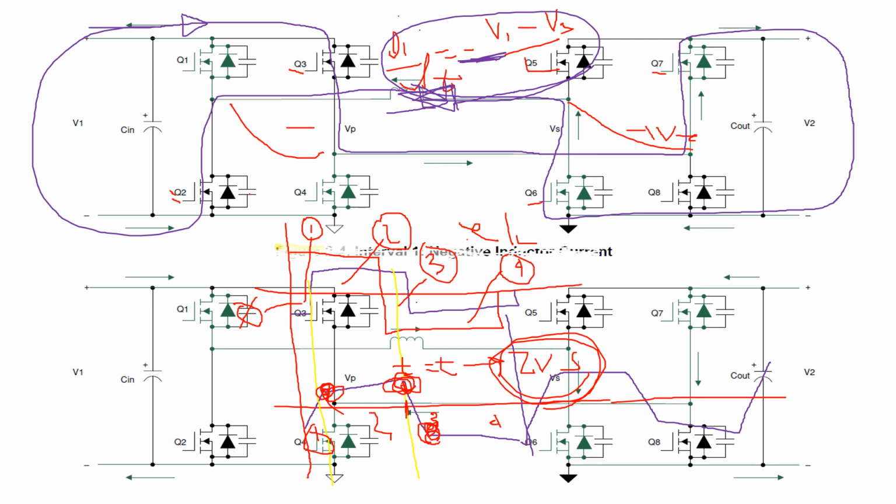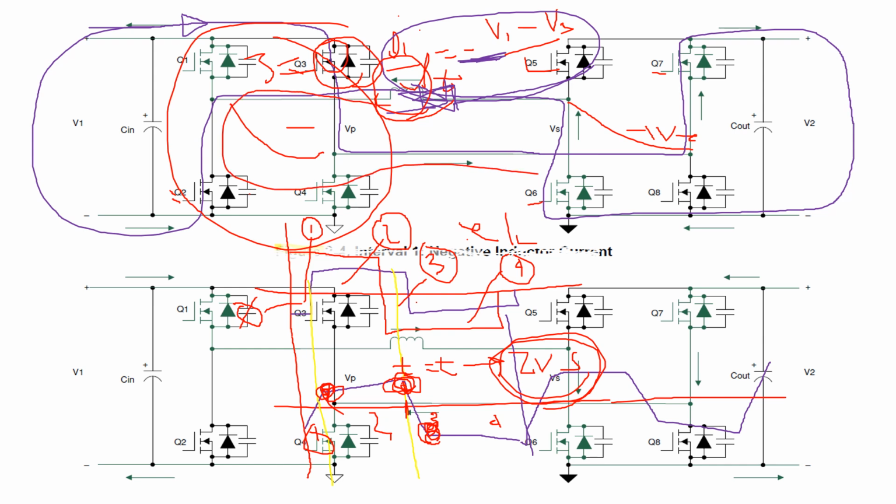It allows for a time delay so that each switch can pick up. When all the switches on the primary side are equal to 0, the inductor current ramps down by supplying current along the circuit. This current charges or discharges the capacitor, a phenomenon known as switching current.